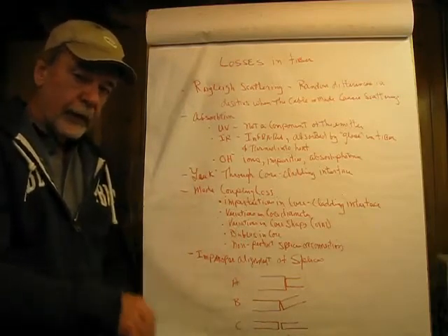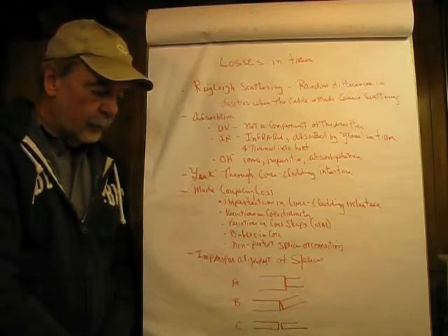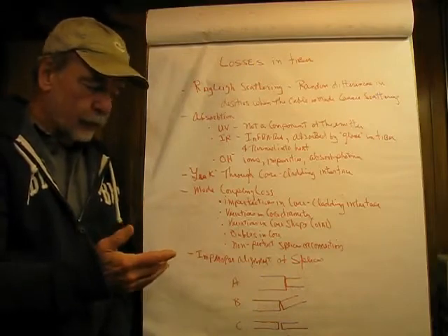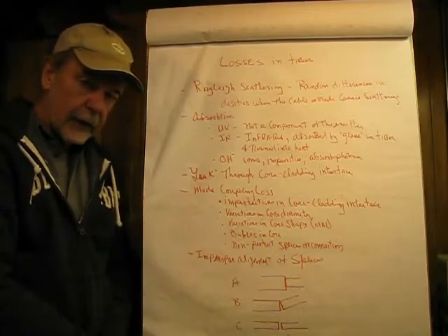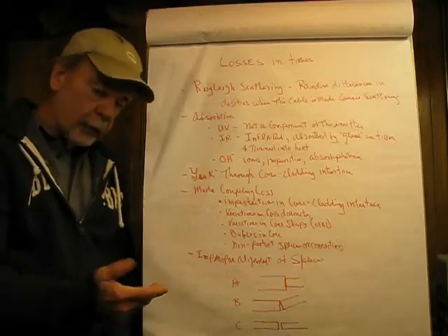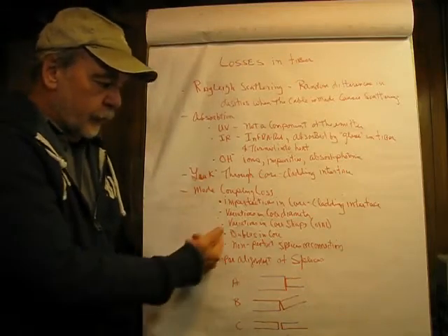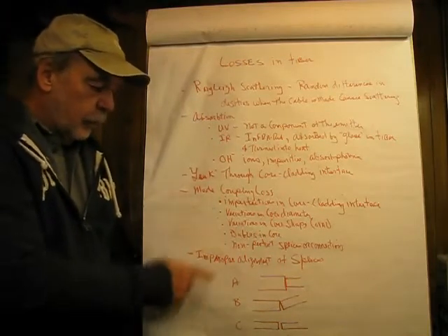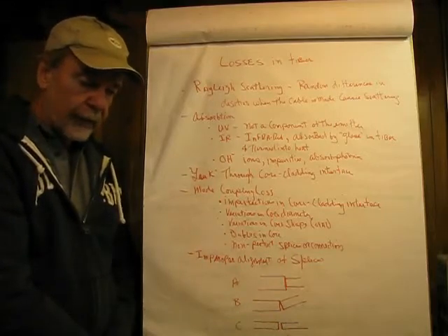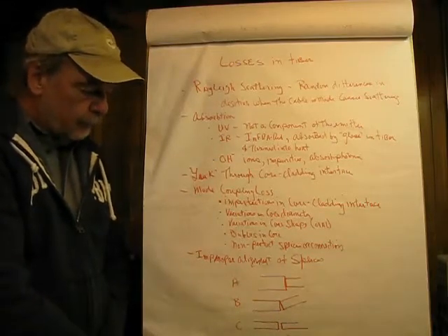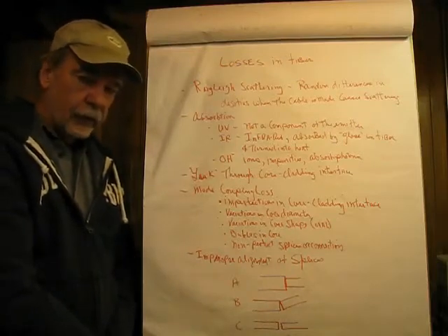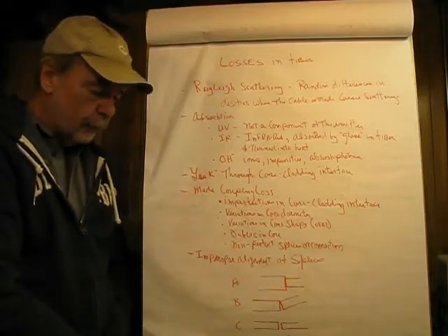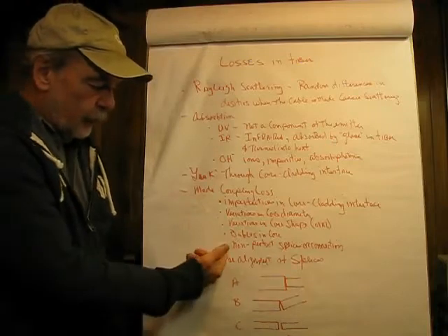So if the core changes diameter, essentially what that'll do is in places it'll change the critical angle, which we'll discuss in a minute. And if it exceeds the critical angle, it's lost in the cladding. It does not come out the other end as a usable component of the signal. We have variations in core shape, maybe somewhat oval, again, bad. And we can have bubbles in the core, and that basically is air. So the index of refraction of the core will encounter places of air where the index is 1.0, and that means refraction rather. And we have non-perfect splices.